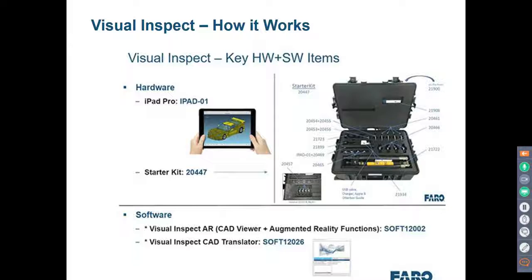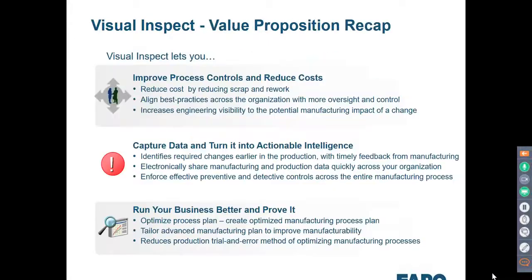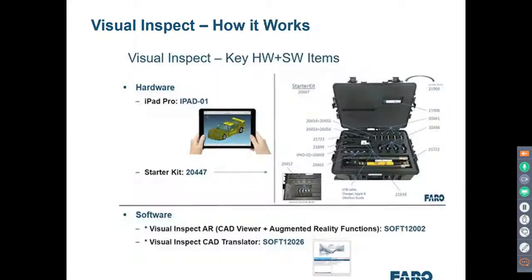And then we have the possibility of using pre-taken pictures. These pictures can be taken on the fly with an iPad camera, or we even have the opportunity to use higher resolution external cameras. With these pictures, you have the advantage that when you place a picture into your model, it's stored there for further reuse. You can overlay or reference this picture by giving detailed pixel points. So you say this pixel point belongs to this CAD point, or if you have markers in your picture, you are able to use the markers there.